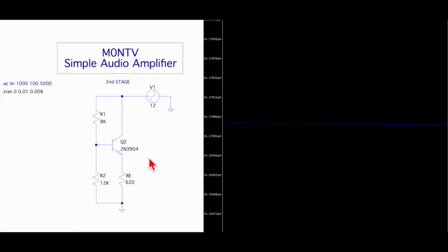We're using the same terms of reference as the last amplifier, i.e. I assumed that beta was 173, even though we know for LT Spice it isn't. And I'm making an assumption based on that beta that the base current will be 57.8 microamps once again.